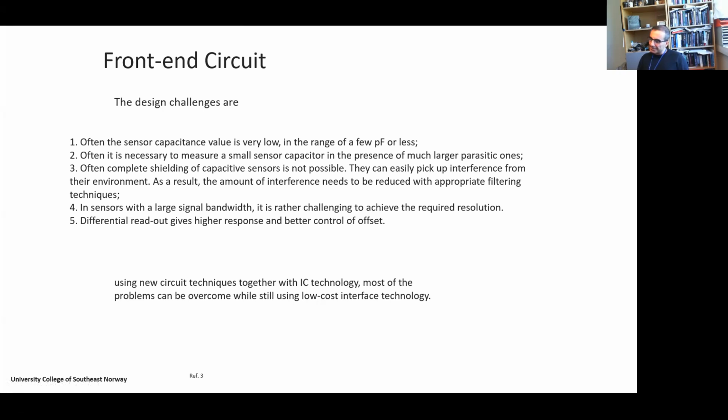To conclude, often the sensor capacitance value is very low, especially in micro and nano sensors. In capacitive ones, they are in picofarads or less. So often it's necessary to measure small sensor capacitance values in the presence of much larger parasitic capacitance values.